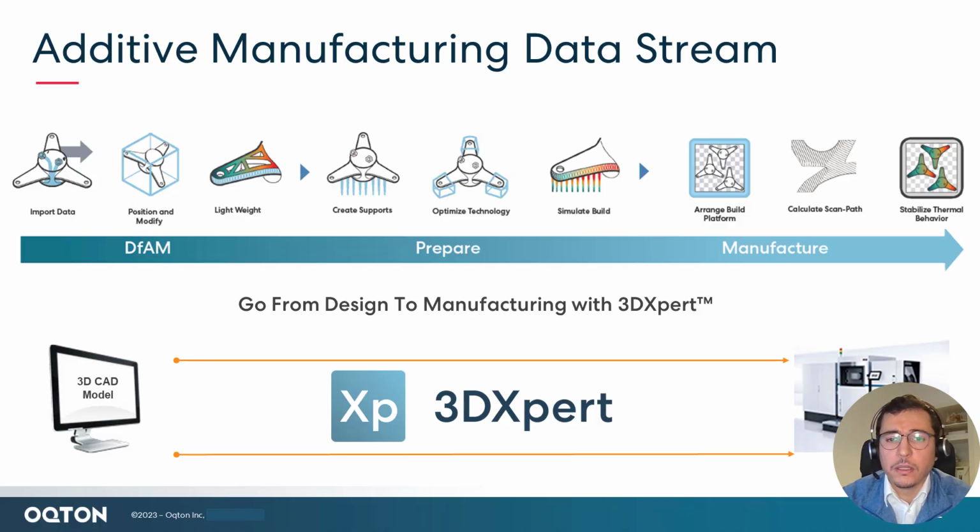You can arrange the build in 2D nesting or 3D nesting, and then you can slice the parts in 3DXpert in combination with the EOS Sprint SDK integration. And how that's done, that's what we're going to have a look at now.